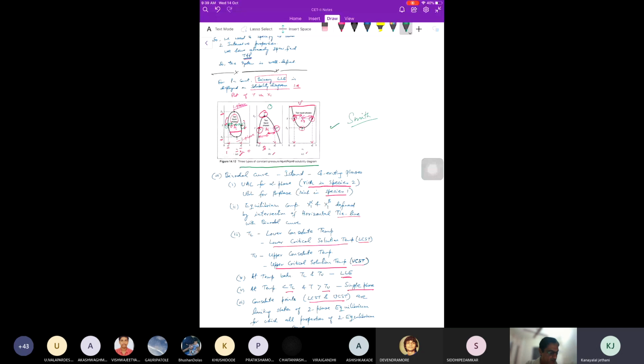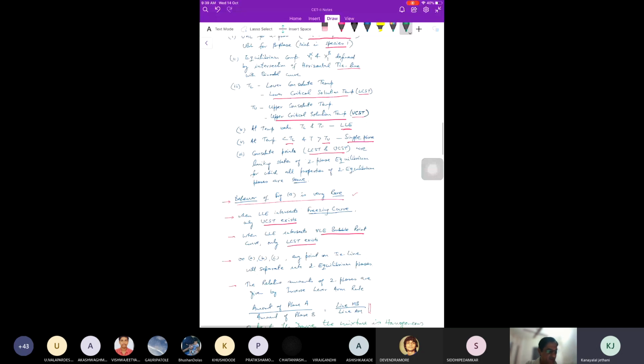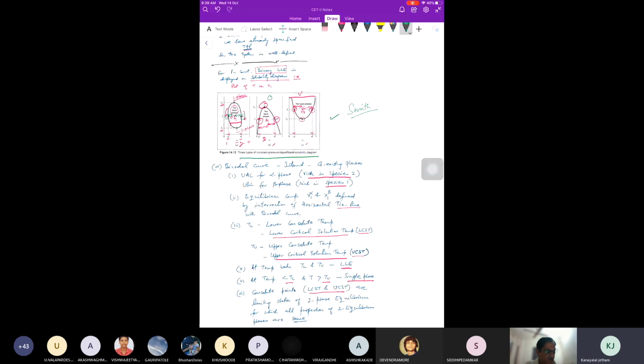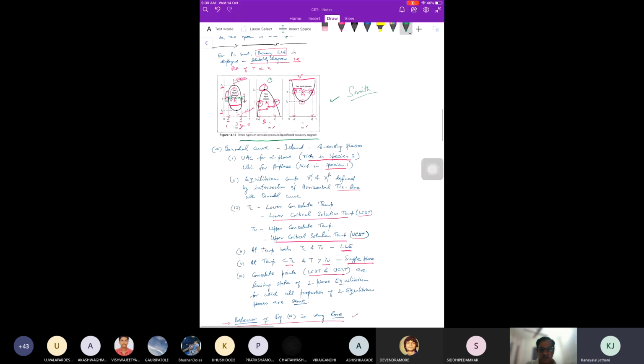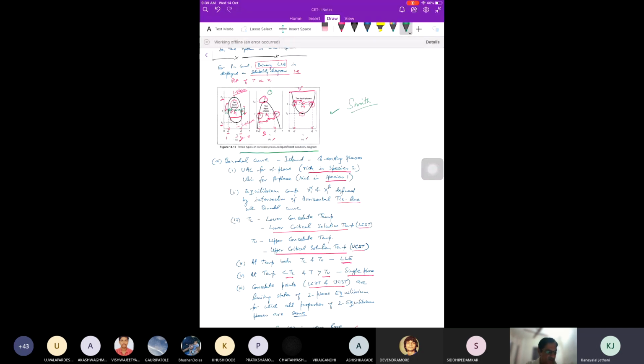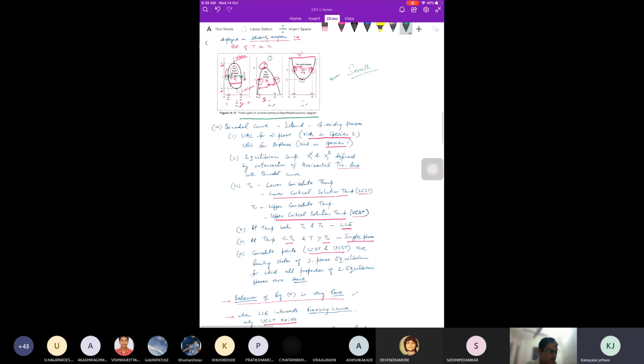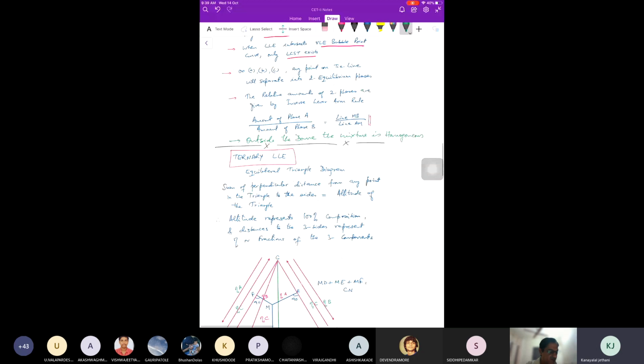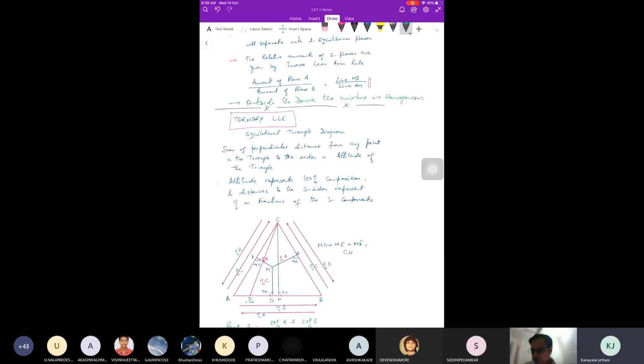Okay, so this is the binary system, but generally there are three components, right? दो में दो का सिस्टम बहुत कम रहता है। Generally in chemical engineering we have three component systems, because you have, जैसे हमने देखा, एक organic layer था जिसमें valuable product था, और हमने water add किया, third component. So there will normally be three components, right? तो उसके लिए ये binary system you can plot on an x-y diagram, but if it is a ternary system then we have a ternary LLE. That was binary, what we saw so far, but then we generally have three components.